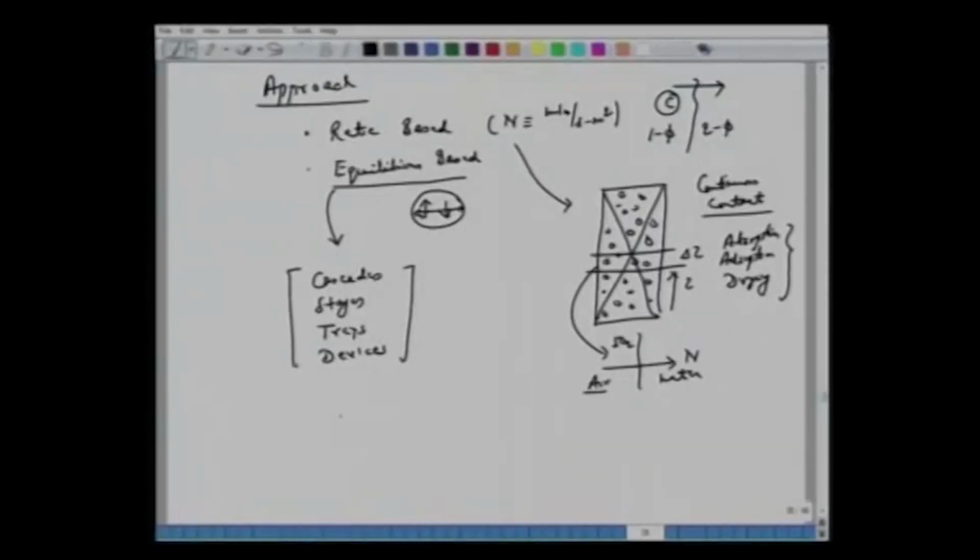So we are looking at trays like this. Liquid goes like this, vapor goes like this. If you look at one tray, there is a pool of liquid. So this water goes like this, air goes like this. It makes very good contact for some time or for some very small height, in which one species has been transferred this way. So here we are talking of equilibrium. The two leaving streams are in equilibrium. You cannot have more transfer of whatever components than what you have achieved.